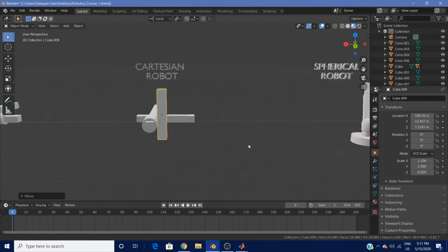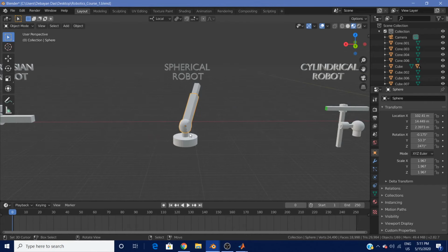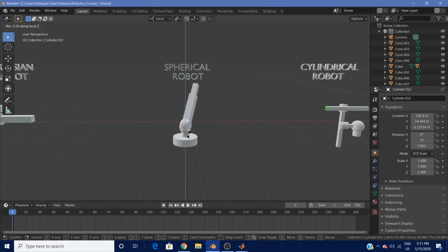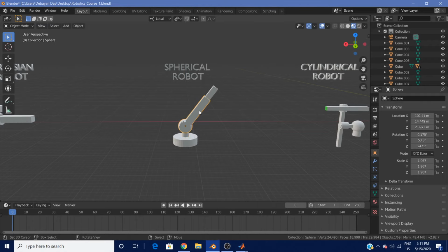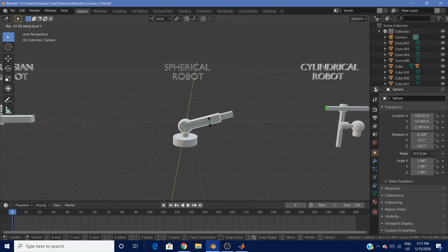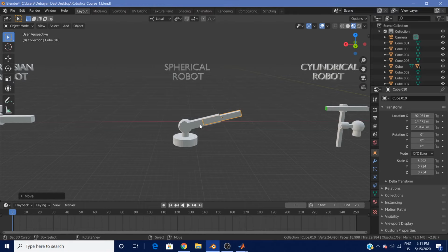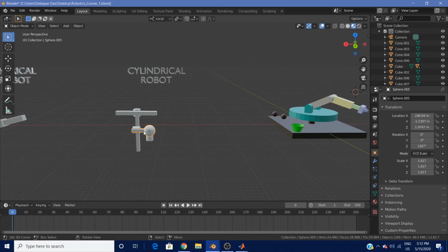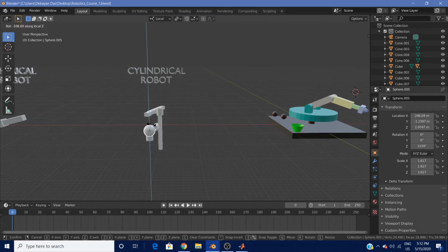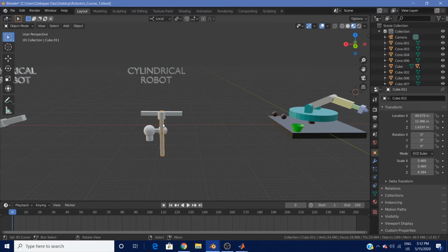and we could get any possible place in three-dimensional space. Another type would be the spherical robot, which could rotate, which would give us a value of theta, a value of phi, and finally a value of r, which would give us anything in a three-dimensional space with a workspace of a sphere. Cylindrical robots, same thing: r, phi, a height, and of course a radius. So that's what a cylindrical robot was.